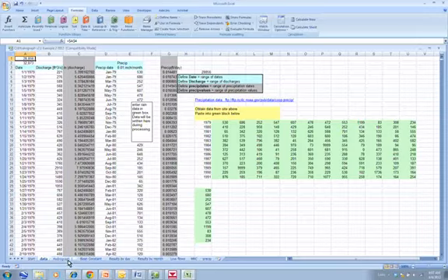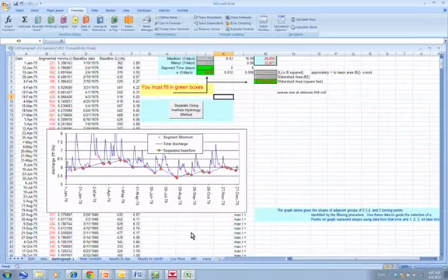And then we'll go here to the next tab, Hydrograph. And this will be the first place where we do some calculations, but we also need to use this to set the rest of the program up. For the analysis, we need to enter three different numbers. One number here in this green box is the watershed area in units of square feet.